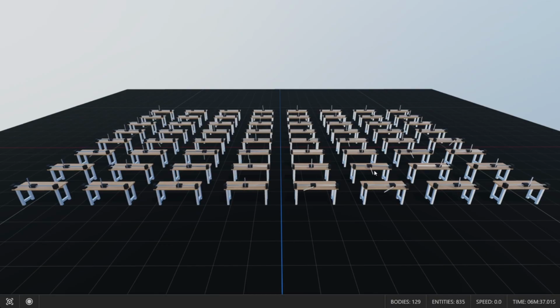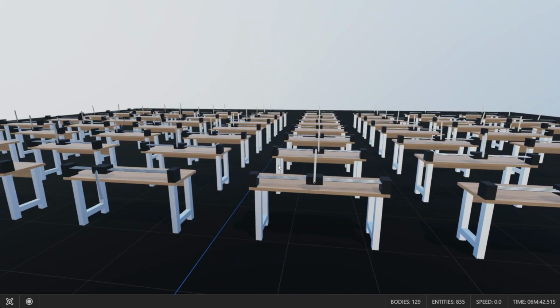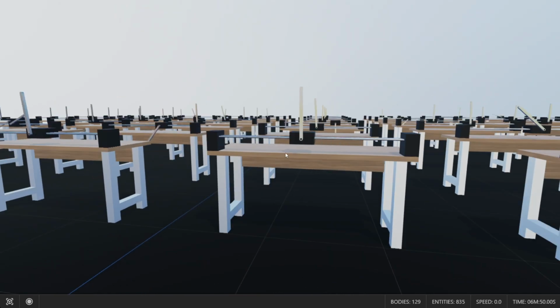And although the poles are balancing upright now, the carts are still shaking quite a lot. This is why we added the penalty term to our reward function. I'll let it run for a little bit longer so you can hopefully see the carts begin to shake less over time.